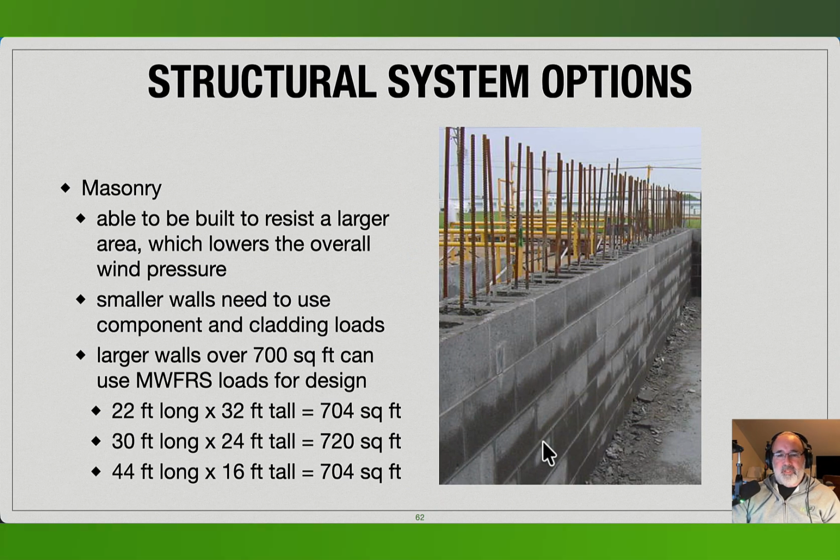One of the unique attributes, I think, of masonry relative to, say, either precast or tilt-up walls is the fact that you can build the walls to a larger area. And I think that is an important aspect of what you can do either with cast-in-place or with concrete masonry or clay masonry elements: you can build to a larger element, which is going to really reduce the overall force that you would have to put on it. And if you really think about that, reduction in force gets into the fact that the whole system could then be responding to the wind load.